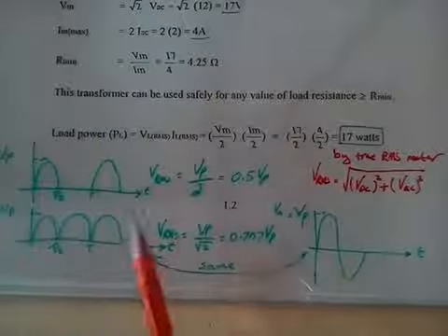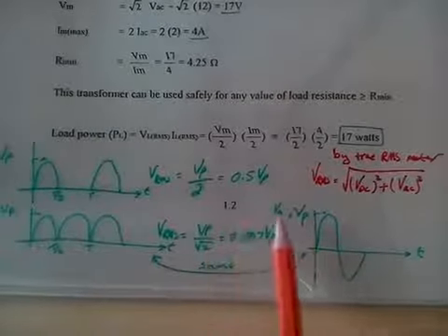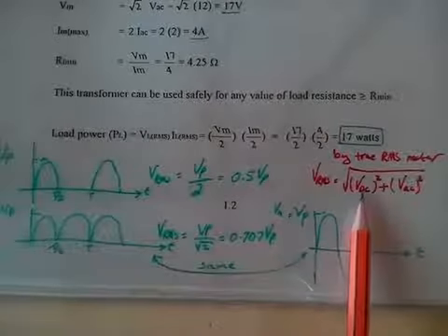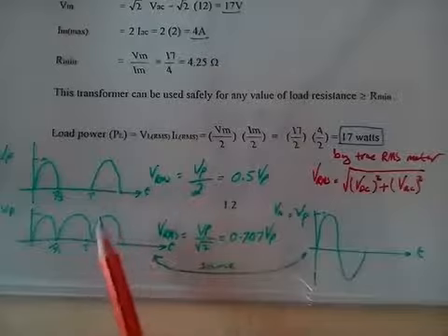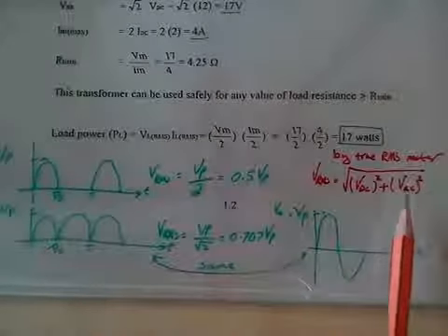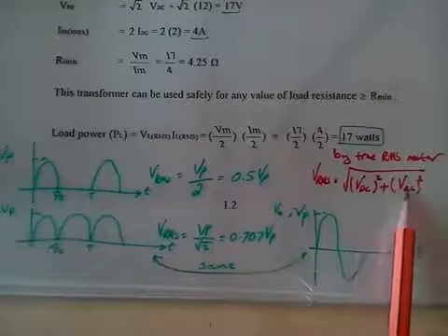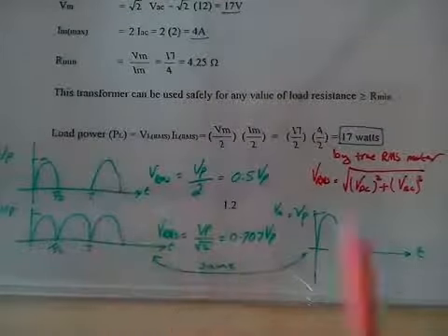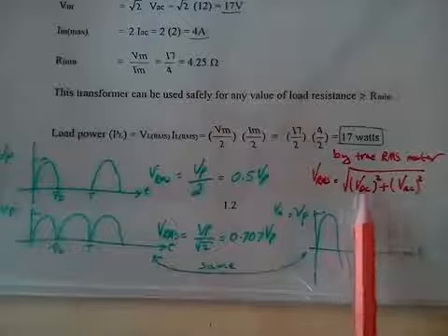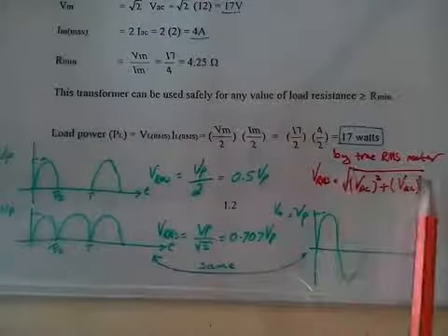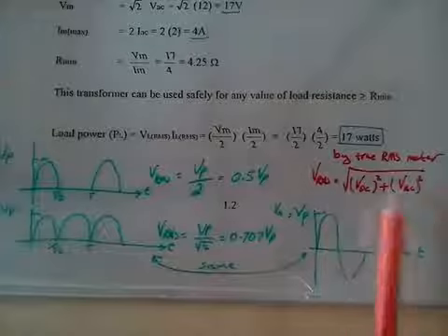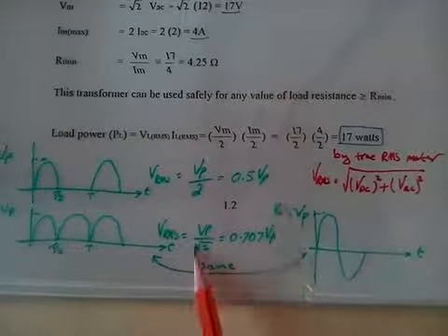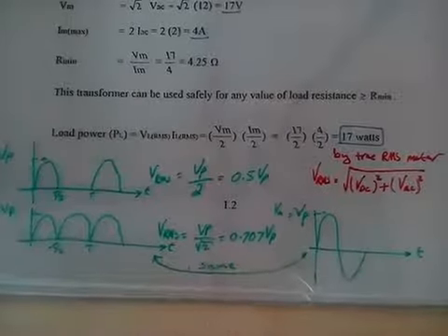Now if you intend to measure these waveforms using a true RMS multimeter, you have to read that VDC first for any of these waves, square it, and add it to whatever VAC is read by that true RMS meter, also squared. Add both of these values together and put them under the square root to get the true RMS of it, which will equal exactly what we have in here.